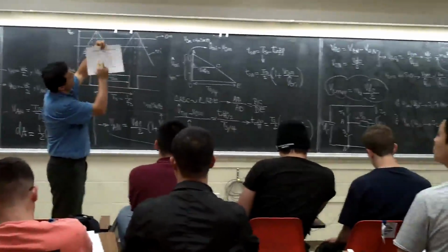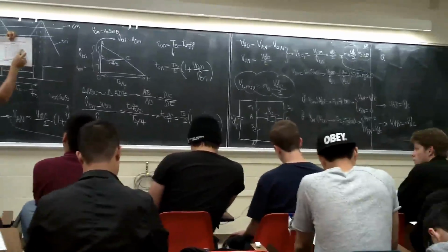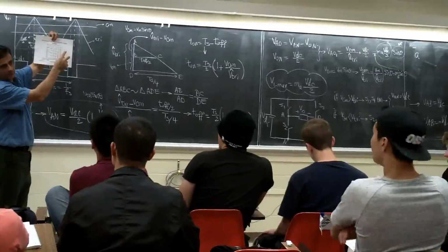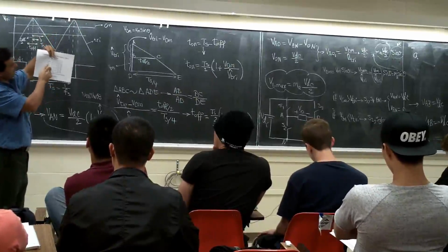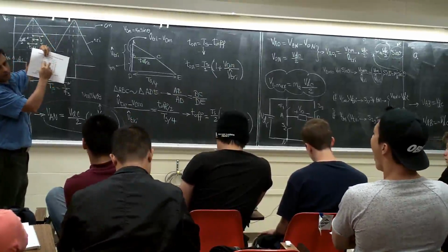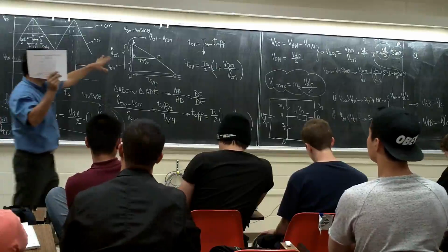If you look at here, it says MA 0.2, 0.4, 0.6, 0.8, 1, right? It stops here. It's not going to go more than 1, because if you go more than 1, it's going to be non-linear modulation, right? Right behind this one, it says the fundamental harmonics. This is normalized. It's not putting the VDC or VDC over 2.